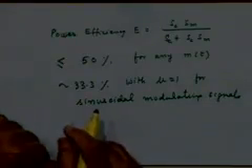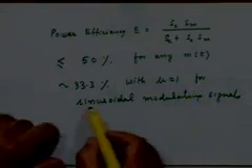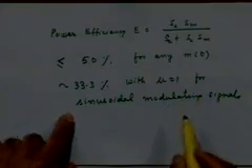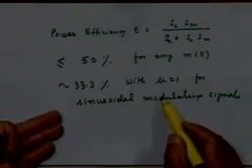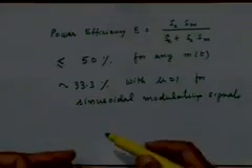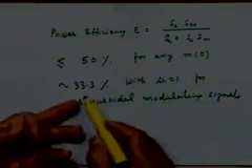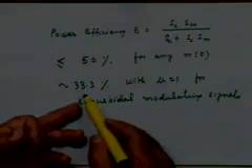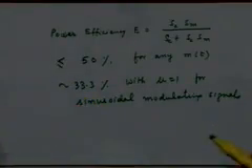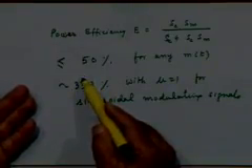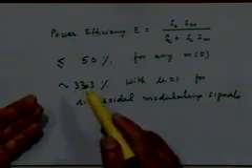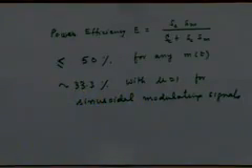Right? So if your message is the one in which m(t) is a low frequency sine wave, and the modulation index is larger, the larger the modulation index, the larger the power efficiency that you will have. So the largest power efficiency that you will get in this case is about 33%. In general, for arbitrary waveforms, it cannot be more than 50%. That can be sure, right? It has always got to be less than 50%. So therefore, there is a significant power inefficiency involved in this process, right?